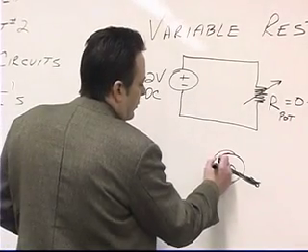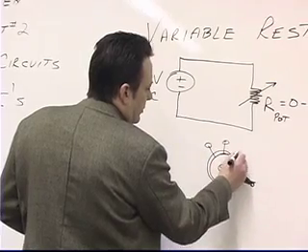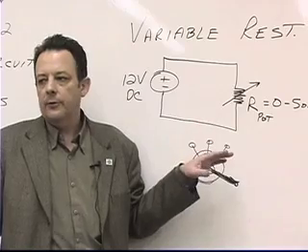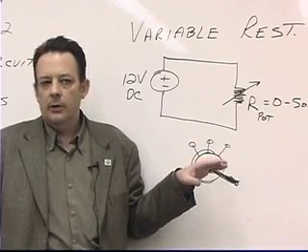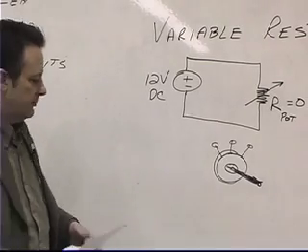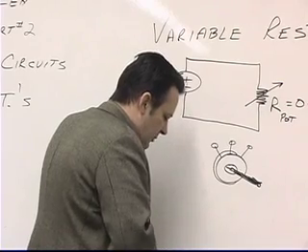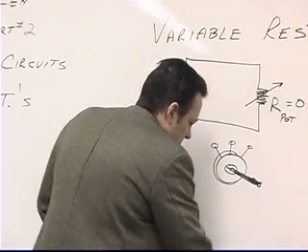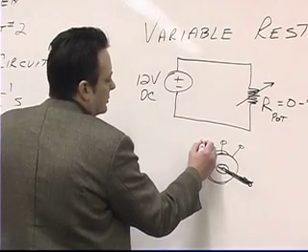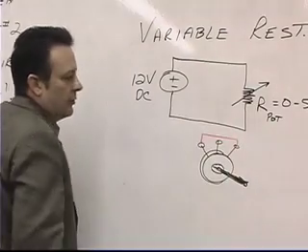that it has three mechanical connections. There's one that's sort of in the center, there's one that's off to the left, and there's one that's off to the right. Okay? Now, if you make a connection, and I'm going to switch colors here to emphasize this. If you make a connection across this potentiometer between the outermost posts, so you connect it like this, and then you stick it into the circuit.